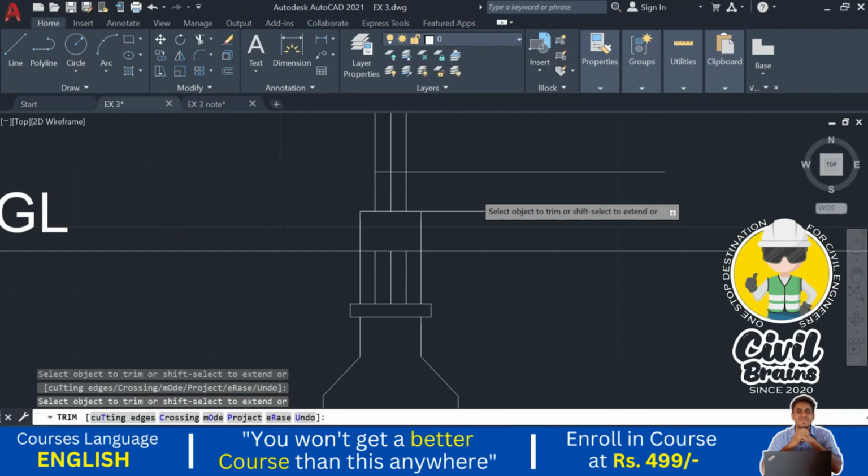The size of the plinth beam we have considered here is 0.23 by 0.23, that is the width of the plinth beam, and the depth is 0.3. So I just take offset 0.3 as the depth, and the width is offset 0.23, that is 0.115. So I just trim the extra part here.